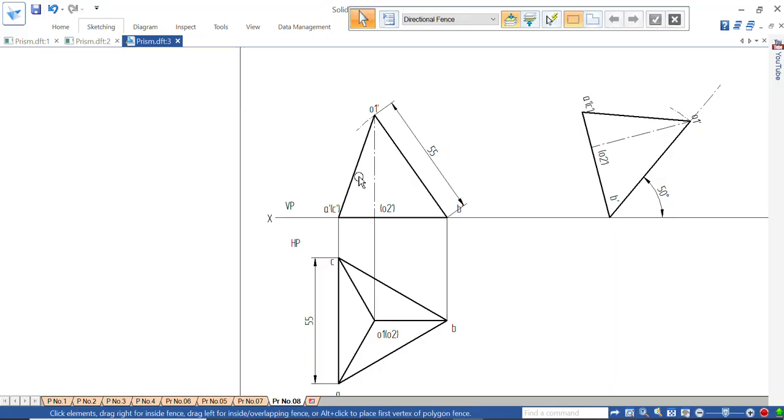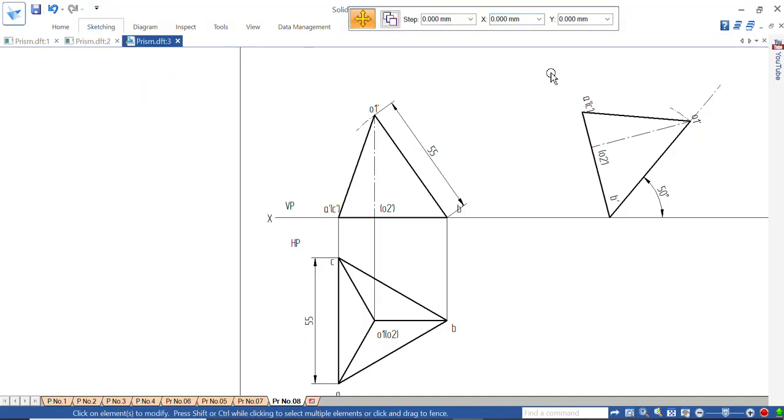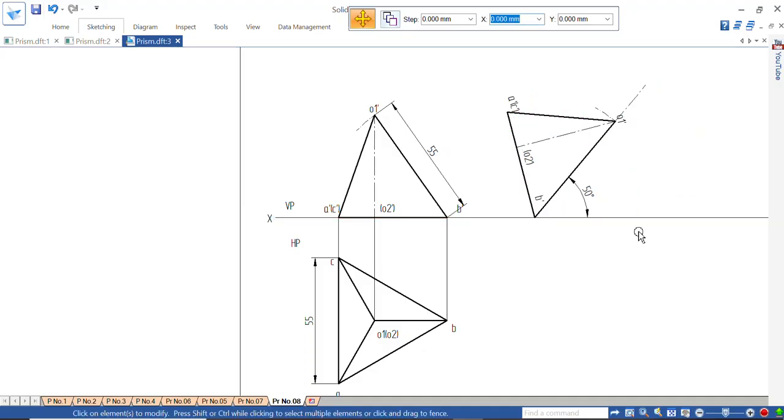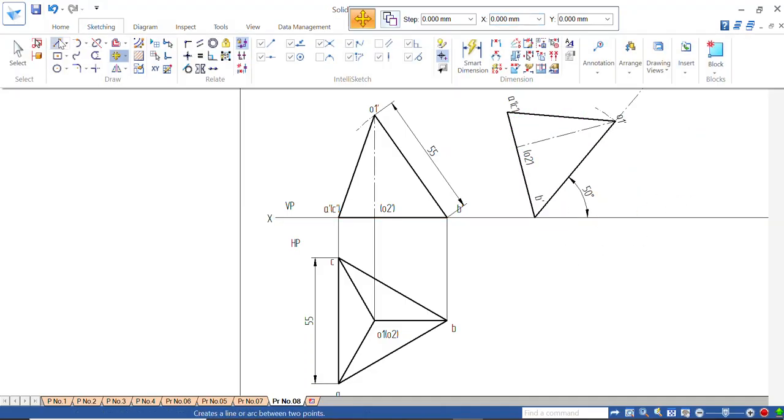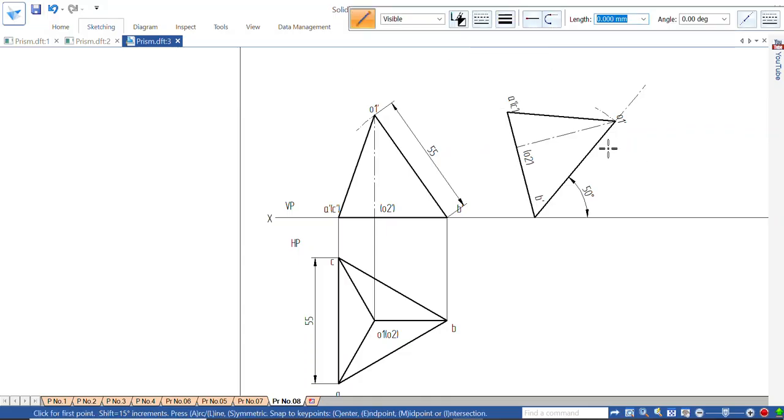Next step, project downwards for the top view. If it is far, as usual, switch off the copy and move this tetrahedron towards the left side, or make it a third position with sufficient space. Next, downwards for the top view, thin line.